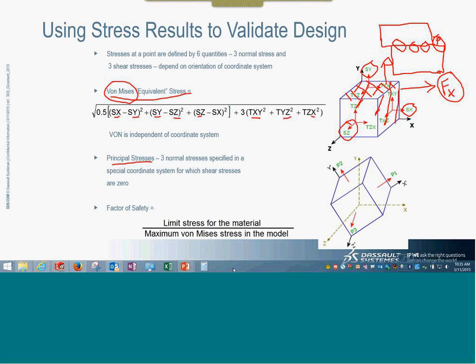When it's about probably 2 million degrees of freedom and more than that, there is a chance of this getting worse and worse and worse. This is a funny thing, difficult to explain in this presentation online, but this is the reality for FEA. So there can be models with 20 elements as well, but it comes with its own cons of losing on the numerical accuracy. It is compensated by different methods, but it is also a ground reality that when we increase the number of elements, the accuracy can drop down. That needs to be understood.